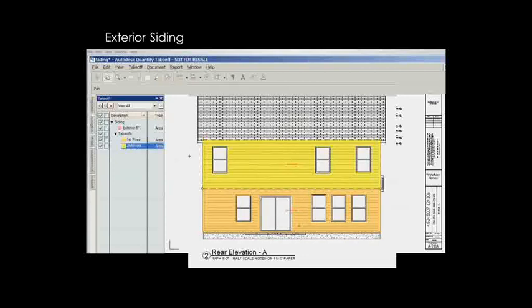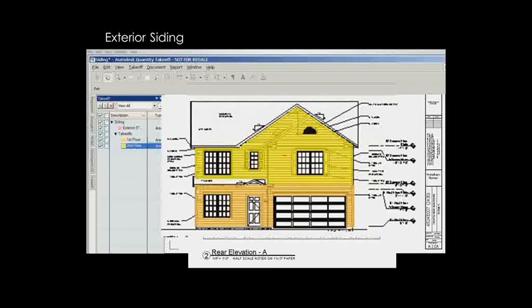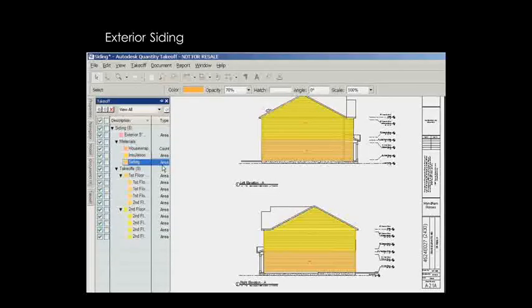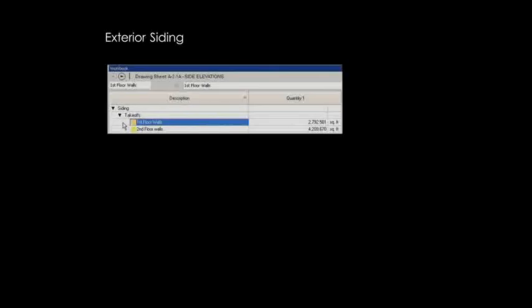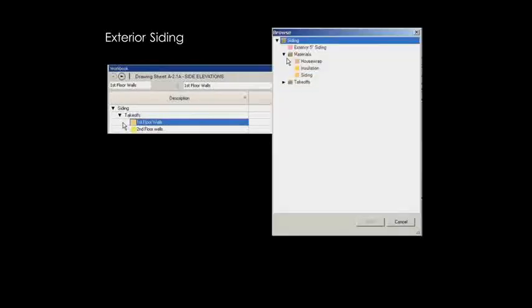You can calculate the area, you can calculate the perimeter, you can calculate any formula that needs to be multiplied afterwards, like to calculate the amount of paint, times the linear square footage or times the amount of elements that you have. So once you have that, like I said, it's similar to what I showed earlier, where you have the category here, materials, house wrap, insulation, siding, and based on that, you start sketching. You have the tools for sketching any kind of shape. You have the tools to remove and edit those shapes, and once you do it, it remembers it.